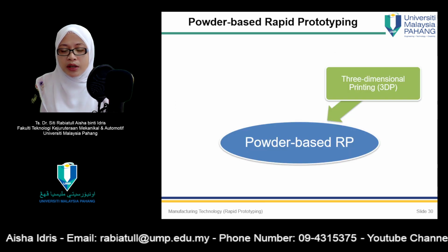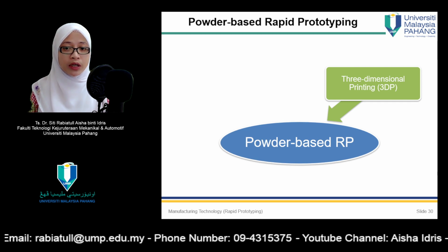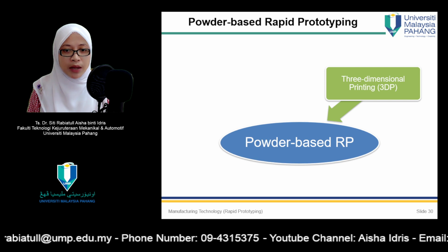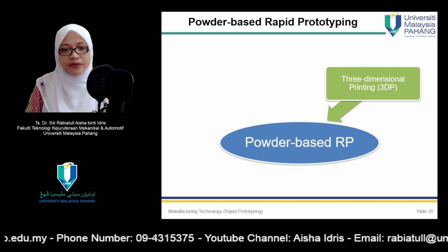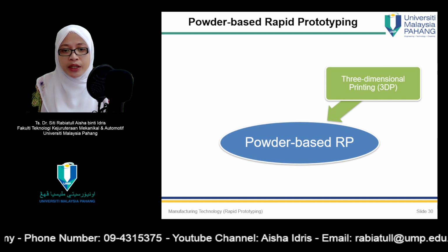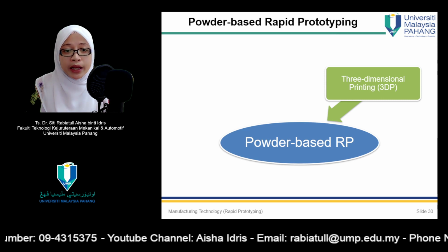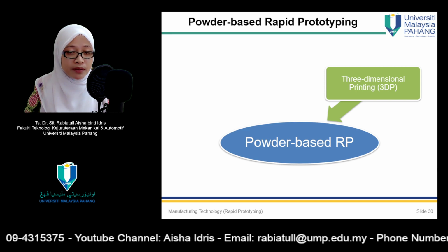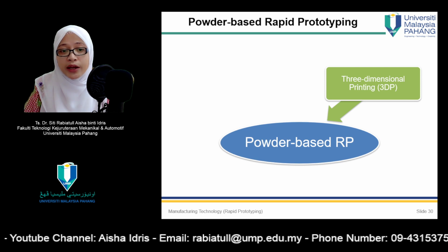Okay, now let's look at 3D printing. This RP technology was developed at MIT, Massachusetts Institute of Technology. 3D printing builds the part in the usual layer-by-layer fashion using an inkjet printer to eject adhesive bonding material onto successive layers of powder.